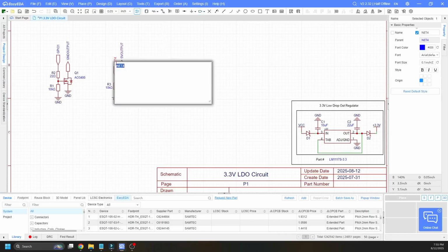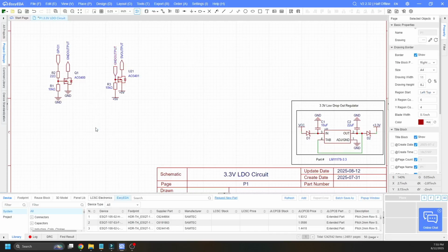And we're going to name this guy ground output. Okay. So what happens here? When we send 3.3 volts from our microcontroller, it comes through here, overpowers the 10K pull down, the positive voltage reaches the gate. The gate now has a positive voltage, which is higher than source, which means this MOSFET is on. The ground can come up, and now this ground output is live. It has a ground on it now.